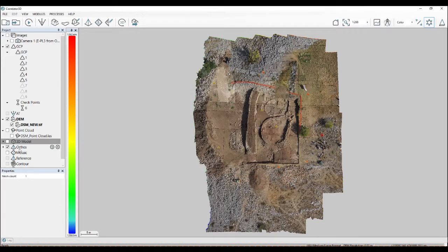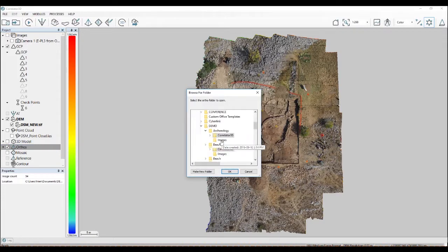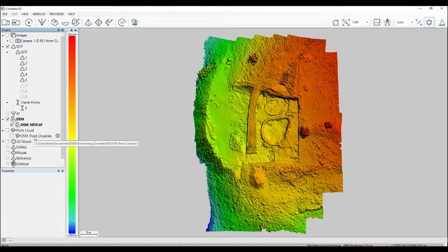Each time I will want to create the ortho, I will have to create a new folder. So I will use that option here to change the ortho folder, and I will create a new folder that I might call, let's say, ortho for the blue band, like this. And this will allow me to export and generate a new set of ortho into a different folder.